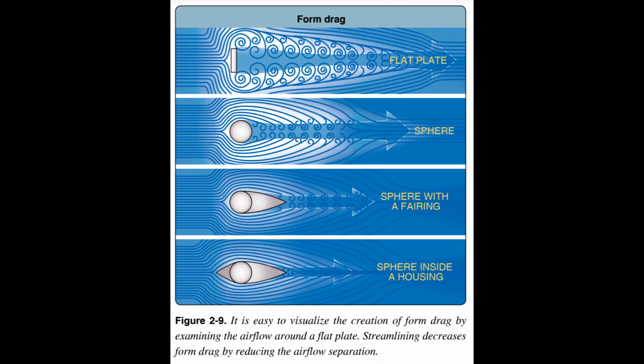Profile drag. Profile drag develops from the frictional resistance of the blades passing through the air. It does not change significantly with the airfoil's AOA but increases moderately when airspeed increases. Profile drag is composed of form drag and skin friction. Form drag results from the turbulent wake caused by the separation of airflow from the surface of a structure. The amount of drag is related to both the size and shape of the structure that protrudes into the relative wind. Figure 2.9.